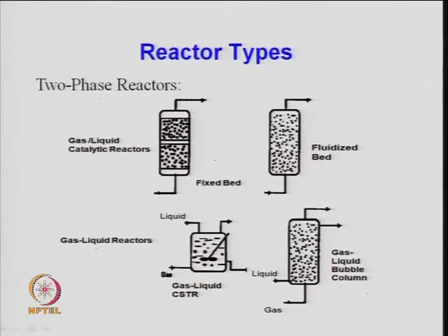these are different kinds of two phase reactor where you have a gas or a liquid in the presence of some solid. So, it is a catalytic reactor. When you have a gas, liquid and solid, it is a three phase system, but when you have a gas and solid, or gas and liquid, it is a simple packed bed reactor, with gas from the top or bottom and the catalyst in the reactor. So, you have a lesser number of resistances.